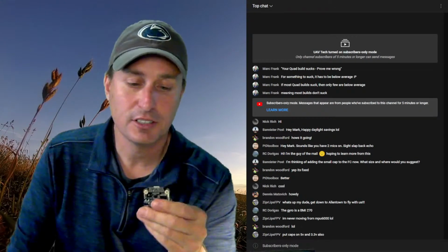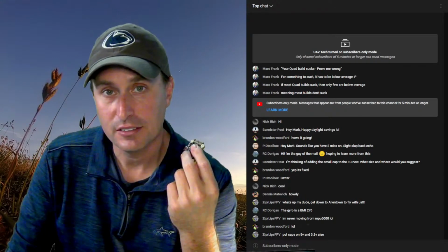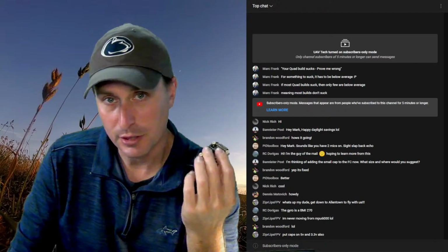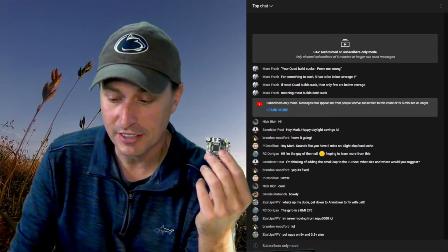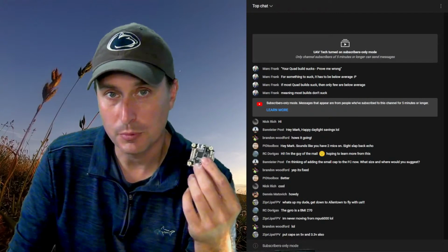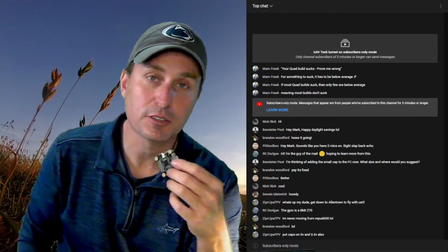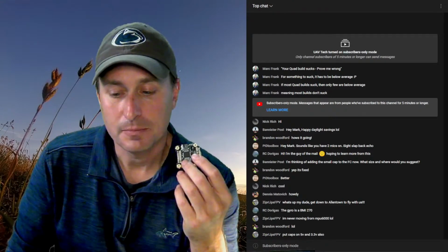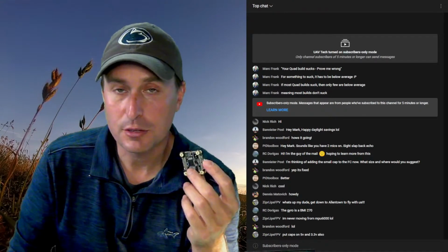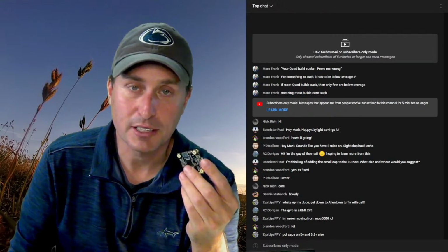For capacitors, again, on the VBAT put a 330 microfarad on there. If you have a 1000, put that on there to start. It doesn't hurt, and you can try the 330 later and downsize it, and see if that improves it. There's no guarantee that is going to make a big difference.